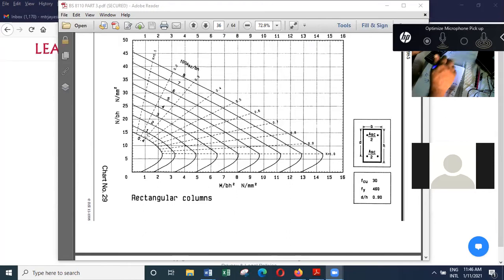And then if you want to optimize, you can consider the next 1 meter. And if the stresses are significantly low, then you might end up with slightly lower reinforcement for the next 1 meter. But on the other hand, what happens is in these walls, always the stresses will reverse.